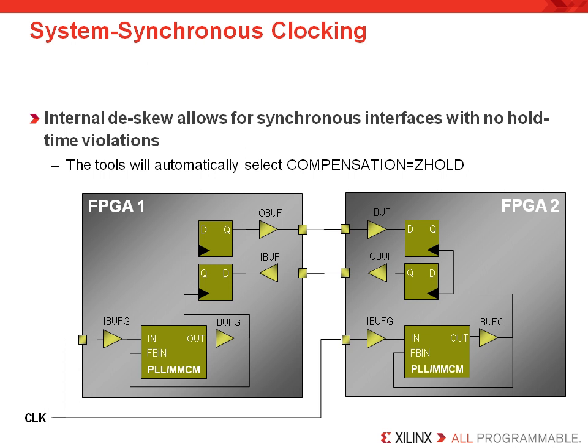Now, by building your circuit in this way, the hold time requirements of the receiving flip-flops are guaranteed to be met, and communication can be done at moderate speeds over significant distances. You should also note that ideally the length of the board routing from the common clock to the IBUFG inputs in both FPGAs should be matched. You should also use the same type of input and output buffers on the data pads to balance the system.